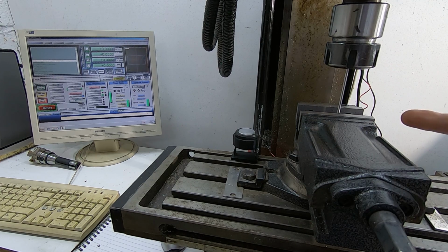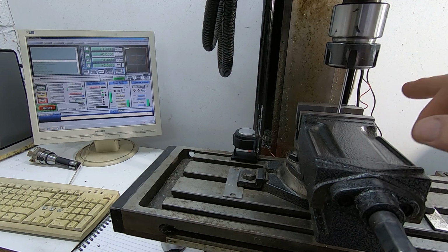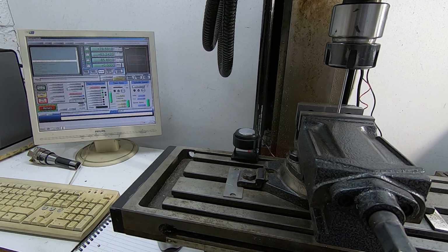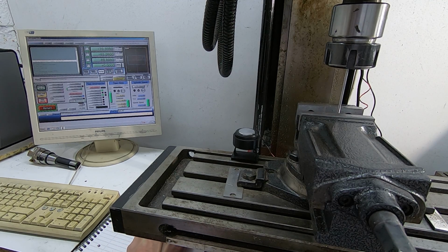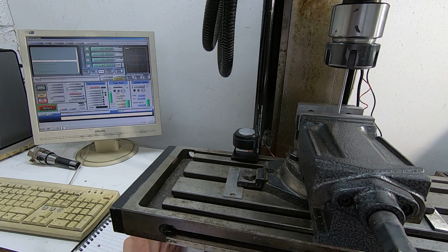So we're now ready to start the milling operation. Before we do that, I'm just going to switch temporarily to the G53 machine offset. The one we're interested in here is the Z offset, and it's -85.891. So make a note of that, and we'll come back to that later on when we've tried running our macros. So we'll switch back to G54. So we're now ready to start our milling operation. So I'll click on Start.